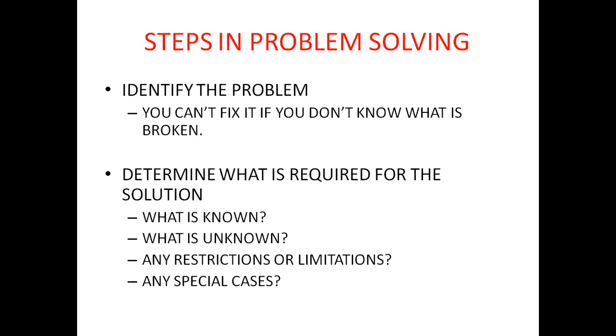First is the known values and the unknown values. If you solve a stress problem, for example a cantilever beam, then the knowns are your force, the length of the part, the size of the part, the shape of the part, and the material of the part. What are the unknowns? Unknowns are the extra forces coming in, or some temperature or environmental changes.